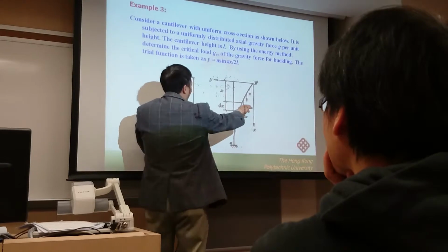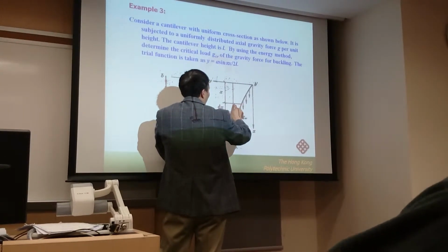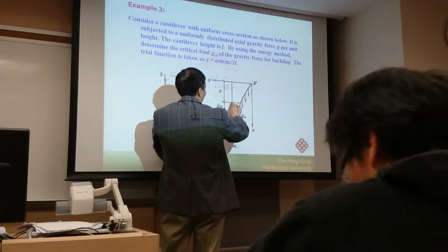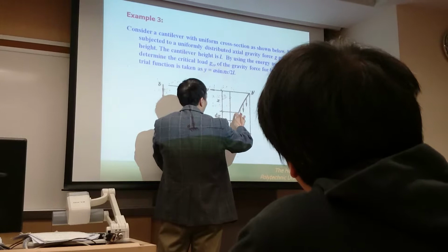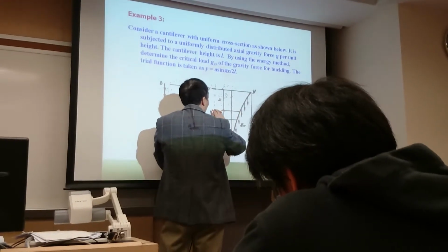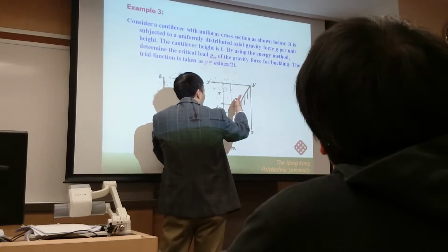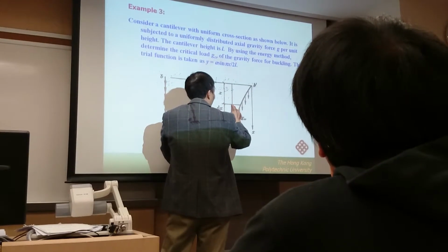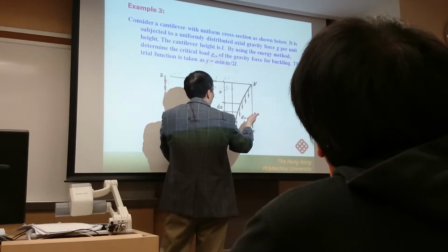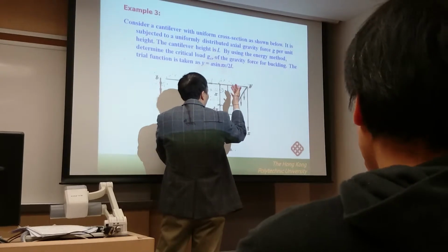When you cut off the section here, for the internal force of this section, if you take the segment above this section as a free body, you can obtain the force equilibrium in the vertical direction. The axial force for this section should be balanced by all external forces applied on this free body.